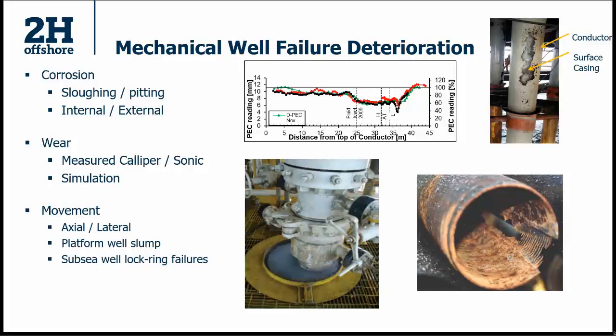So we should be modeling pipes with the correct wall loss assumption, because they're only as good as their worn condition. You can't assume that the pipes are new. That can either be measured or it can be simulated, or even just assumed, which is quite a common method of accounting for drill-through wear.